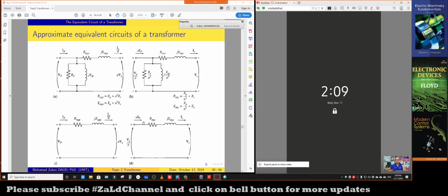This is the most simplified one, without the effect of the excitation current, where the parallel branch here has been neglected. There is no parallel branch for this one, for the sake of easier calculation and easier representation of the transformer.